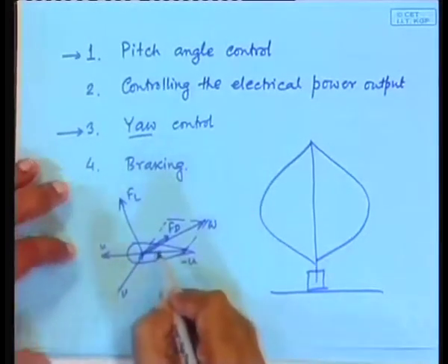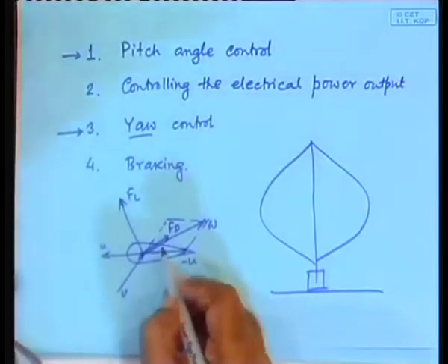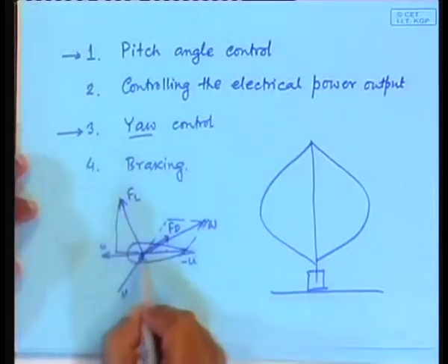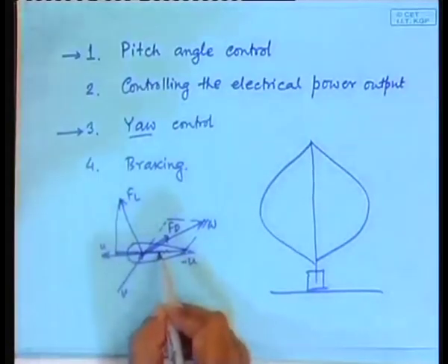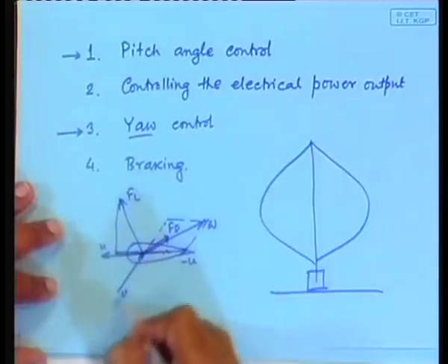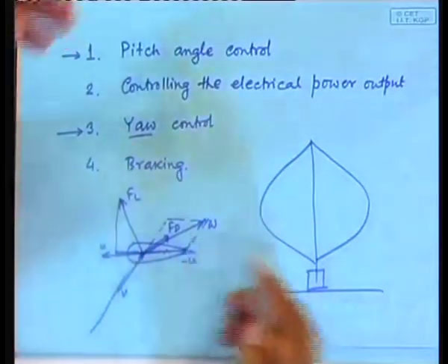right. So, the actual force that produces the torque is the difference between this and this. This will produce the torque and this will try to resist. The difference will actually produce the net torque, and if this becomes much larger, you will find as it goes around this whole circumference that the net torque becomes almost 0. So, at very low wind speed it has no torque, at very high wind speeds also it has no torque, at 0 u it has no torque, only at an optimal condition it has torque. So, it has an inherent protection, does not break by itself, clear.